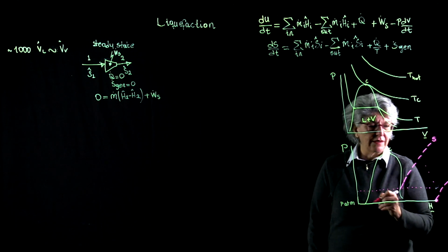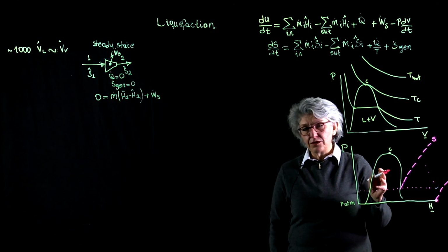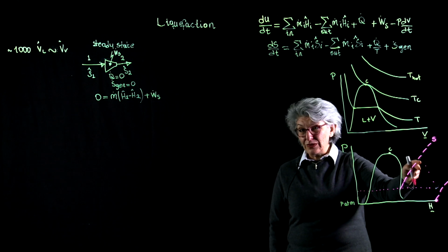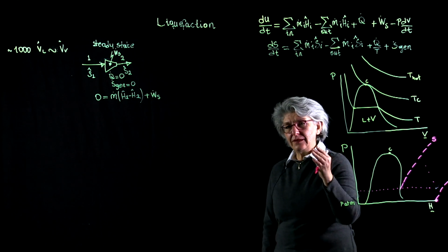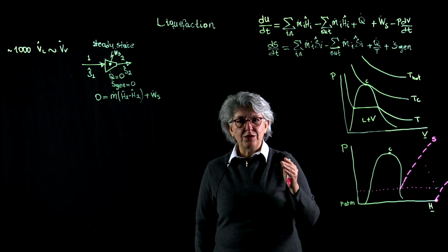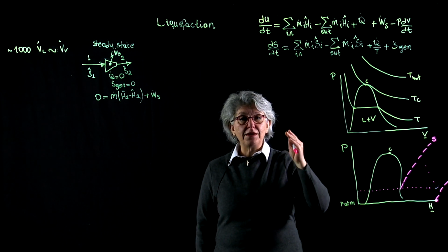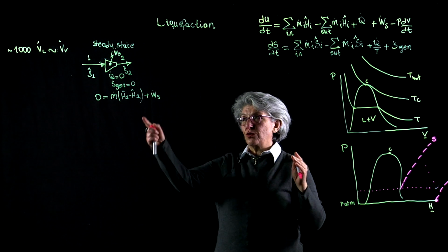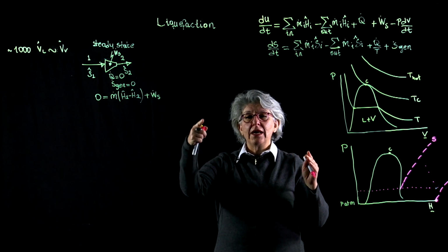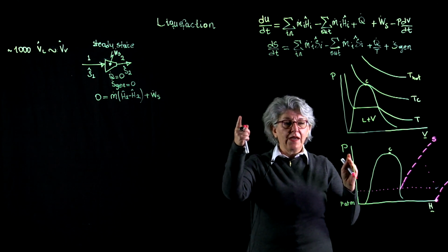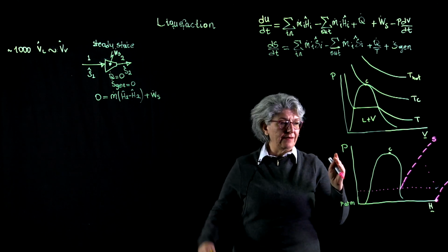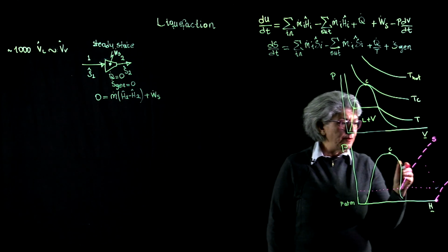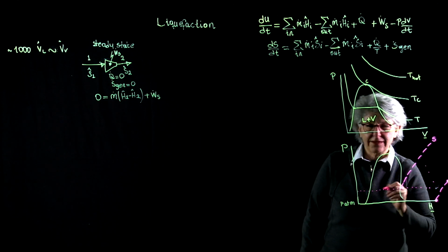is going like this. Now, I don't have much space on that end of the light board, but also adiabatic and reversible compression is going to load a lot of energy in terms of work on my fluid. As a result, at the exit of this compression process, my fluid is going to have a higher temperature than the inlet, and I really don't want my temperatures to go that high, which makes me stop at a point like this, right?